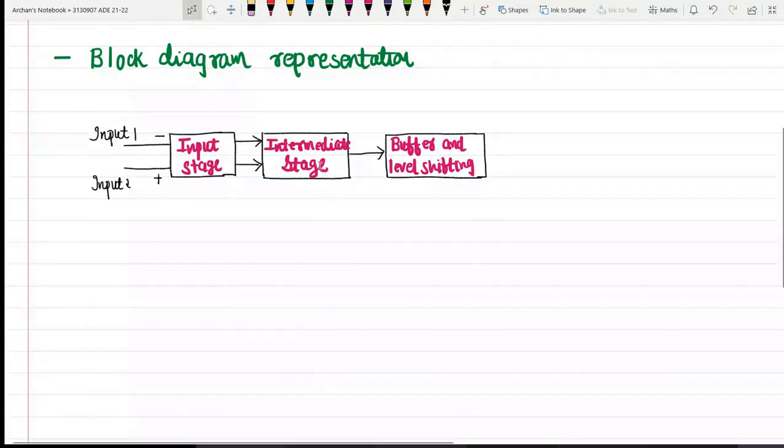As the operational amplifier amplifies DC signals also, coupling capacitors are not used to cascade the stages. Hence, the DC operating point voltage level of the previous stage will get applied as the input to the next stage.